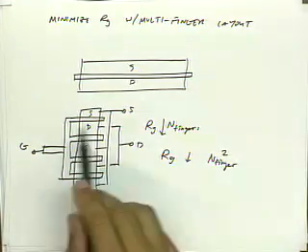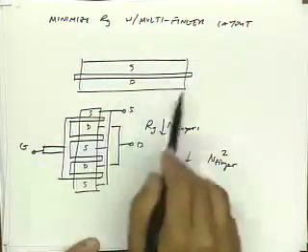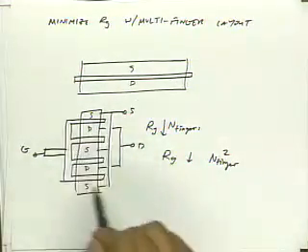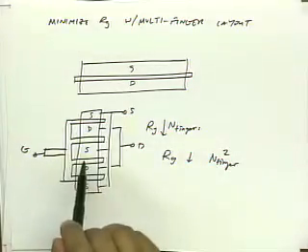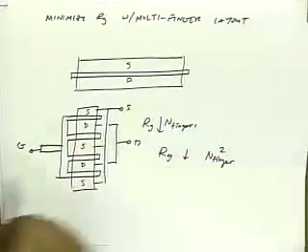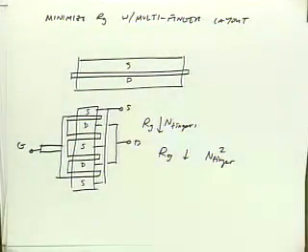So this layout is much superior to this layout. So first thing you do when you do high frequency layout is you go in and make all your transistors multi-finger devices to make them nice and low gate resistance. Okay. Questions?